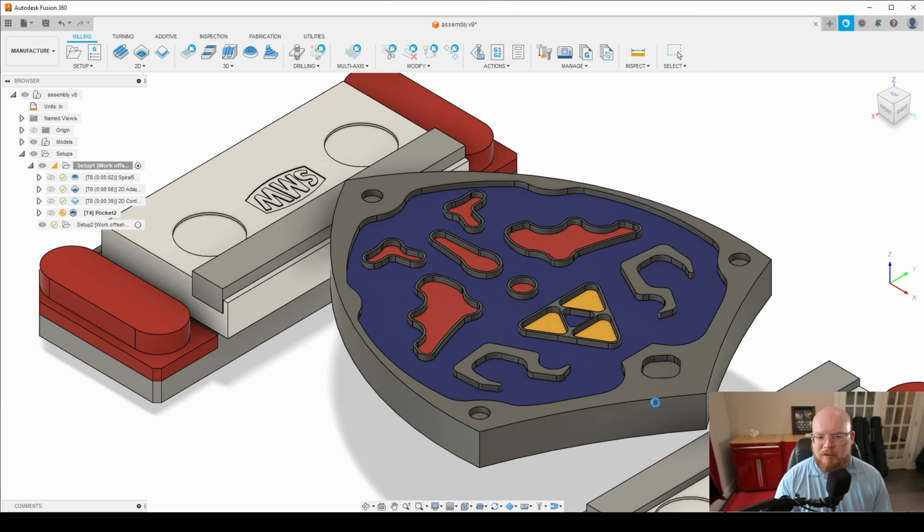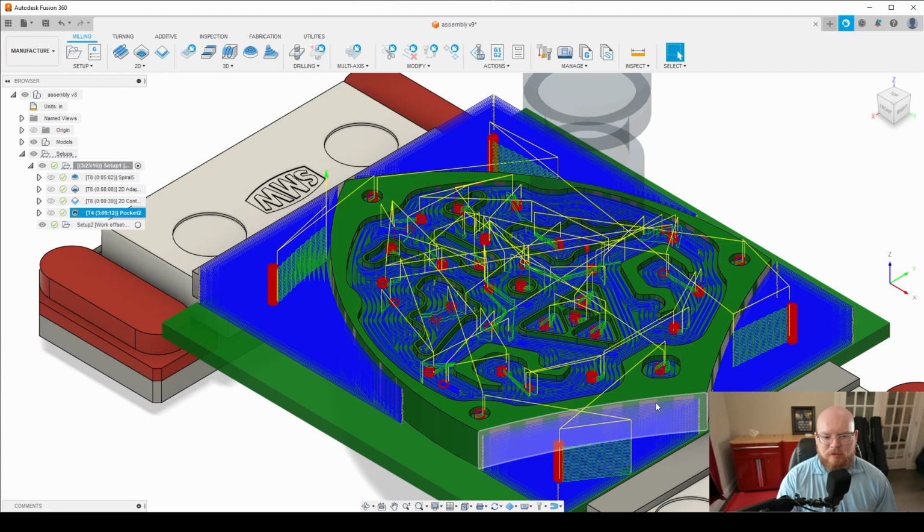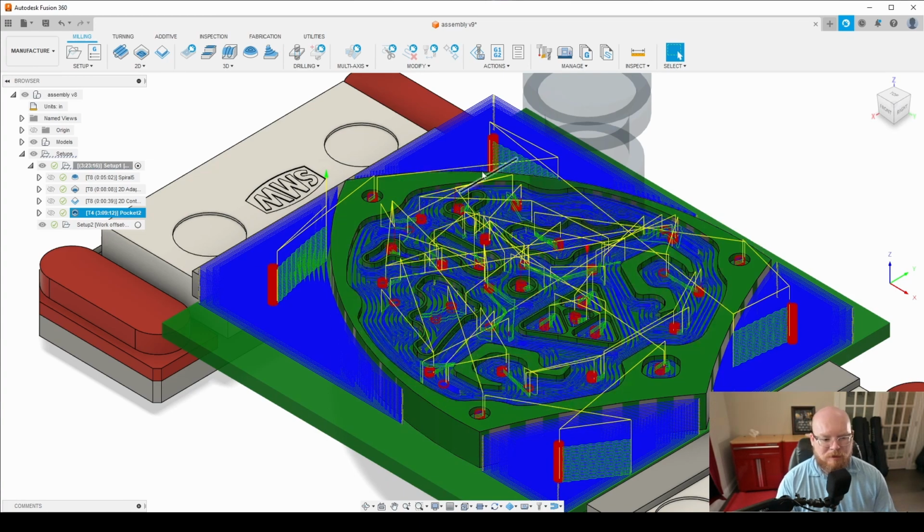And now you'll see why we want to go back and change that geometry tab. Again, because it's a 3D toolpath, Fusion took into consideration all of the geometry of our part for us, and it tried to machine the outside, and that generated a 3-hour toolpath, which is definitely not what we want.